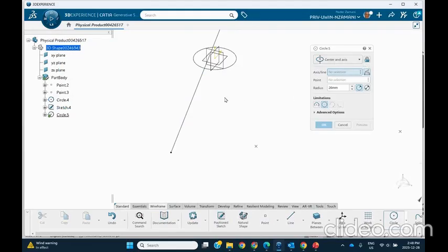So for the axis, we select this direction. For the point, we select, for example, this point. What happens is that it drops perpendicular to that direction, whatever the location of the intersection is. That point here is going to be the center of the circle. And of course, this is going to be the radius. All right.